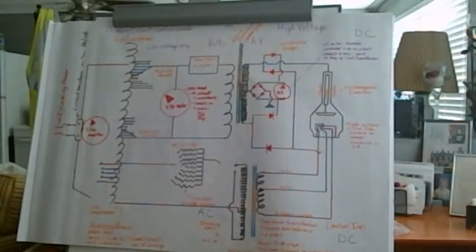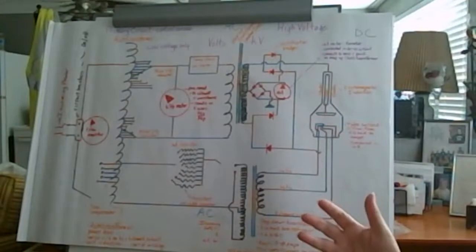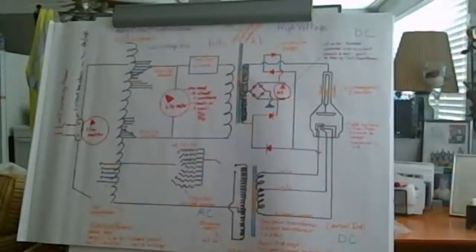Some of the equipment you have nowadays, you don't see that distinguishing between the major and minor, but when you're changing it digitally, you'll have one set of buttons where you can make the changes incrementally, like 1 kV at a time, fine-tuning, and then you have your major where you're changing your kV 10 kV at a time.